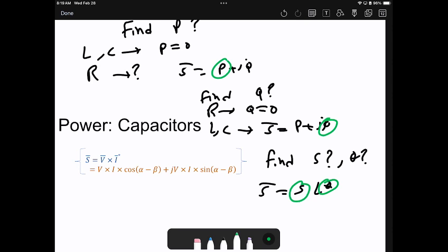So whatever question you see, find real power, reactive power, apparent power, power factor angle, complex power, the first step is to find S bar first. Then, after that, you can convert this to polar or rectangular. You can even write the conversion formulas in your note card, polar to rectangular, or whatever you need. Then that's it. So you are not even required to memorize this. Any questions?